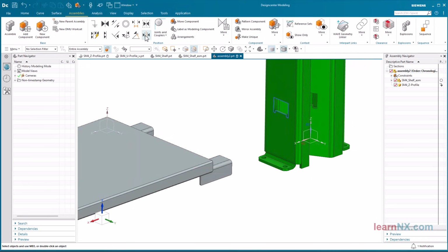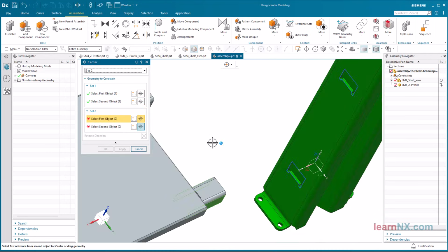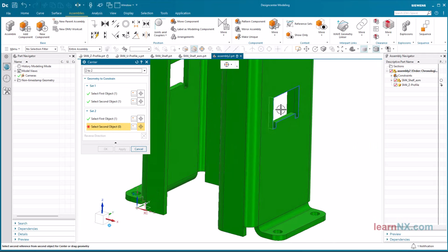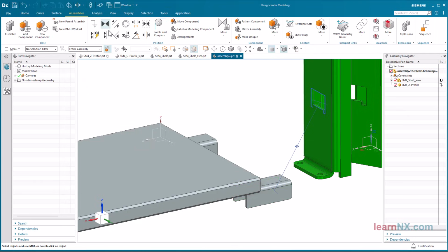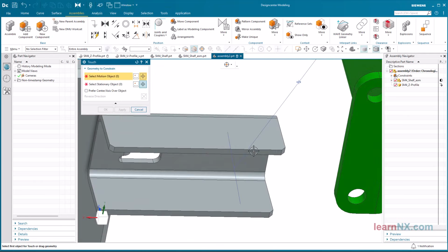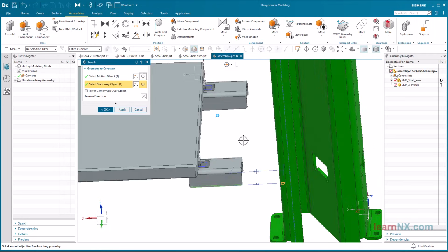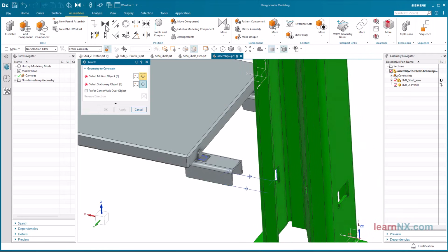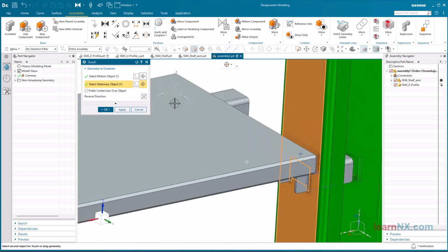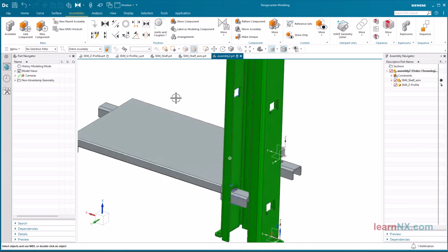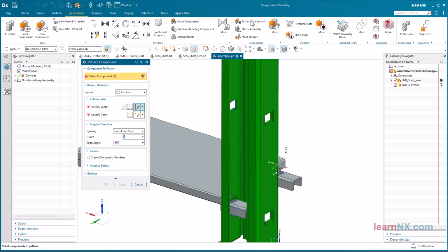The U profile is smaller than the hole in the support. With the center option, two surfaces of the U profile can be aligned centrally with two surfaces of the hole. The touch option is used for the two remaining alignments. Important. This aligns the U profile to a copied surface. The parameters of the copies can therefore also be used to copy the shelves.